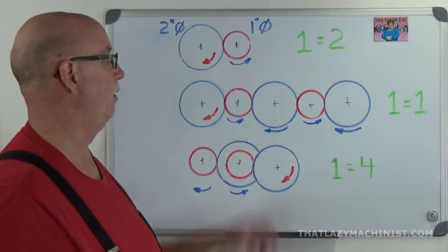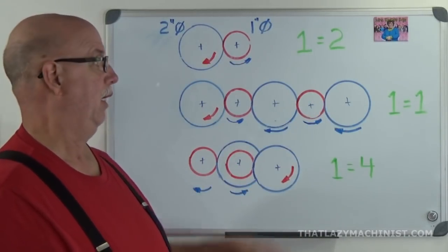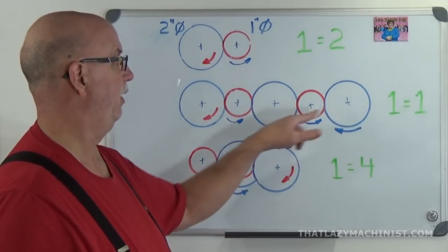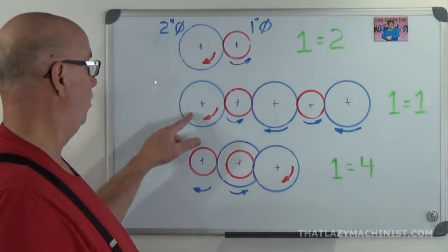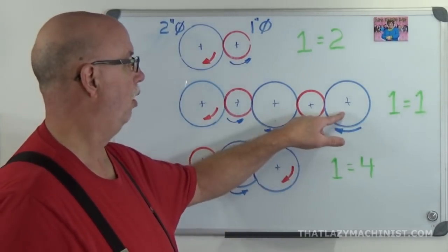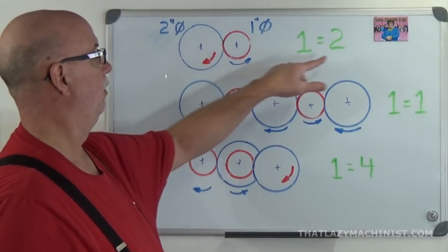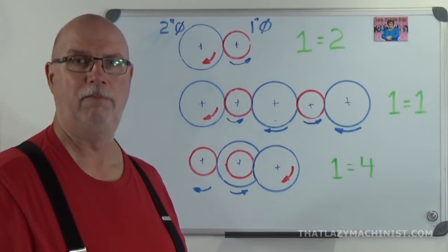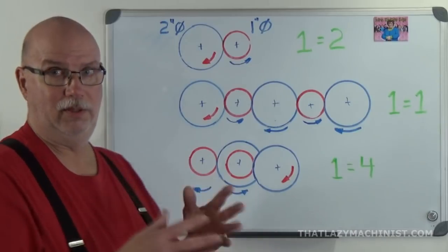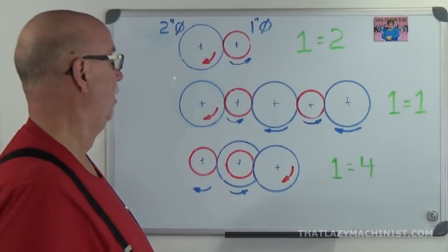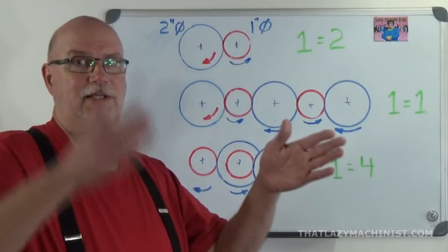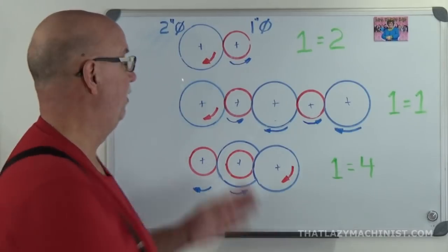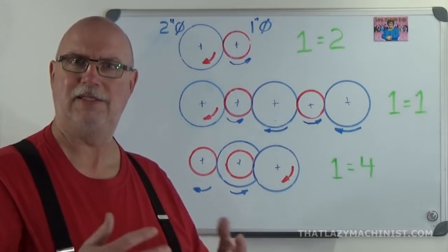And let's push it further. We go to this last gear. And this last gear is going to bring everything back to 1 to 1. It's going to annul the advantage again. So 1 turn of this gear is going to equal 1 turn of that gear. This is a 1 to 2. This is a 1 to 1. And that's an important notion. With gear trains, with gears that aren't on the same shaft, all gears in between the first and the last gear are idler gears, and they serve no purpose other than to bridge the gap. So that's an important note.